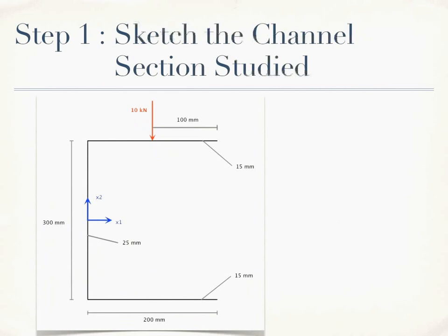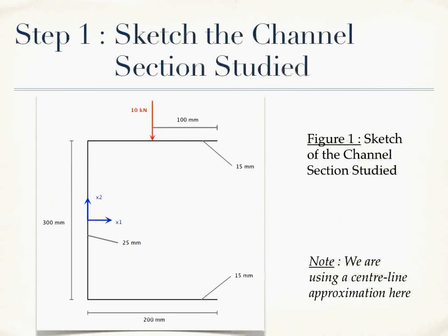So the very first step, we sketch the channel section, and also we use the centerline approximation in our calculation. We also define the x1 and x2 axis. We assume the origin is at the center of the web.